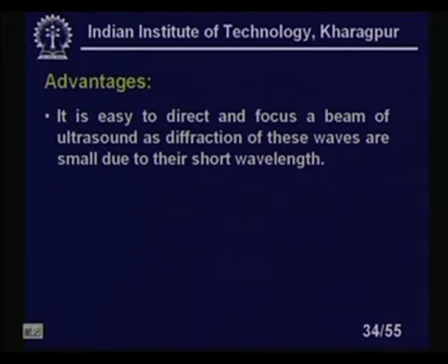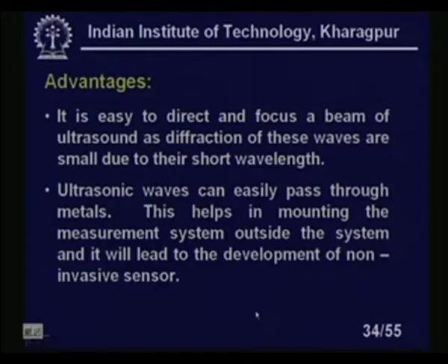It is easy to direct and focus a beam of ultrasound as diffraction of these waves is small due to their short wavelength. Ultrasonic waves can easily pass through metals, which is a great advantage. This helps in mounting the measurement system outside the system, and it will lead to the development of non-invasive techniques of measurement, or non-invasive sensors. This is the terminology we call non-invasive measurement, because I can install it outside; I do not have to install anything inside.